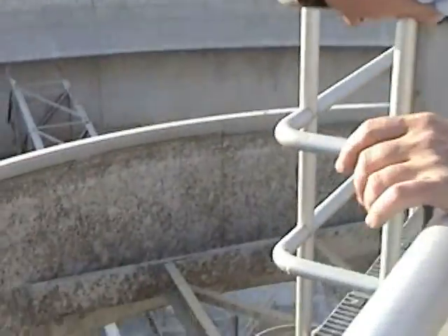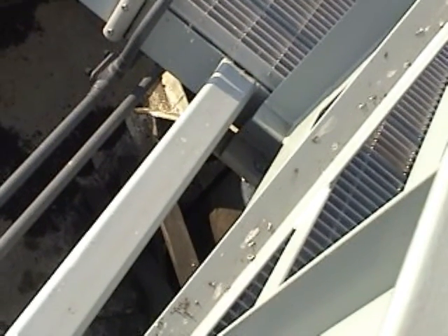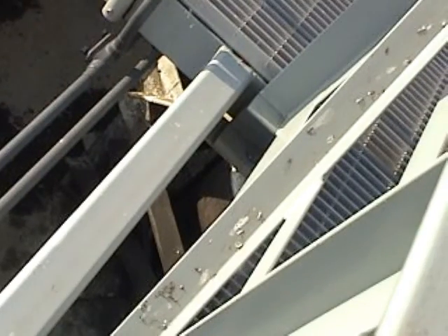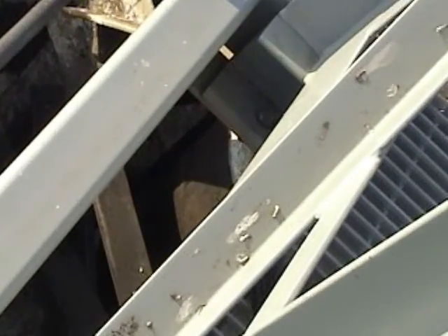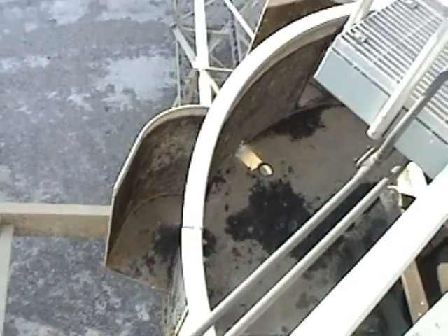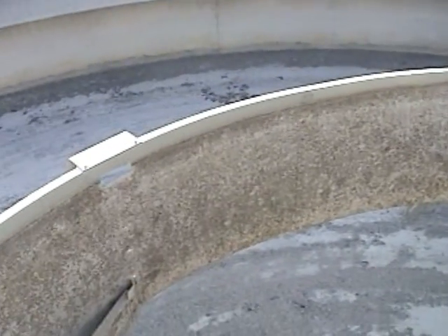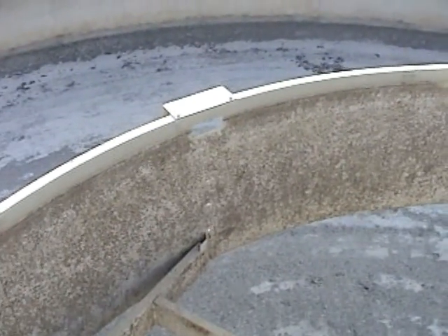And let's see, it's kind of hard to see down in there, but what'll happen is the mixed liquor flowing from the aeration basins will flow up that center column, and then this baffle here will spread it. It's trying to evenly spread it over the surface of the clarifier. And then this other ring on the outside keeps any foam or floating debris trapped in the center ring, and out of the surface of the secondary.